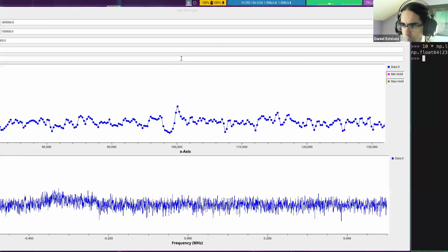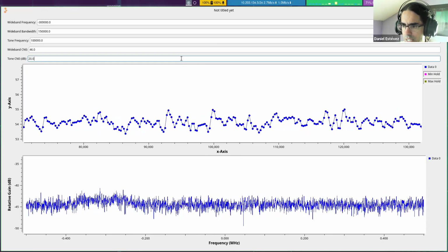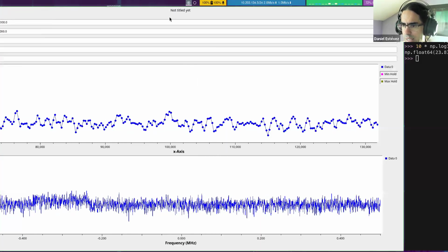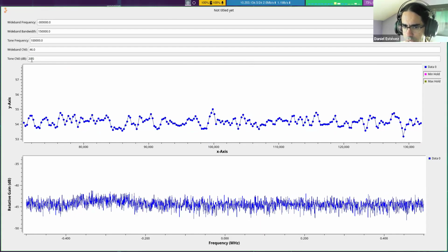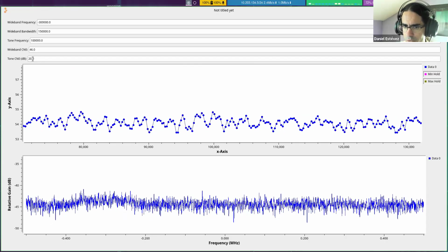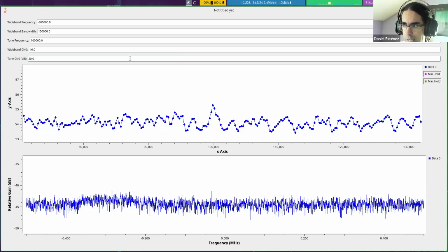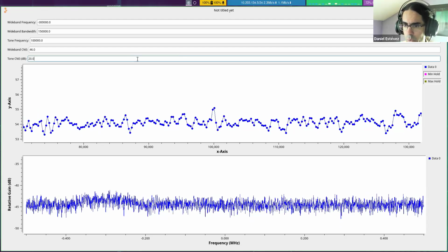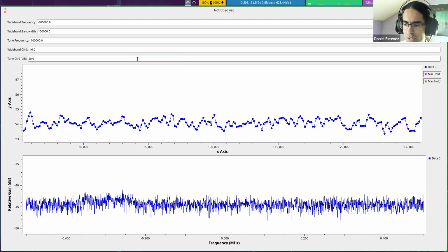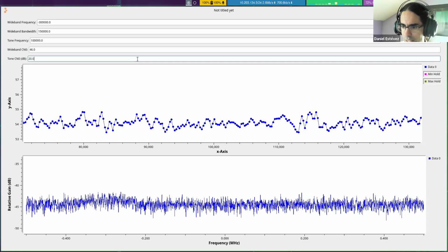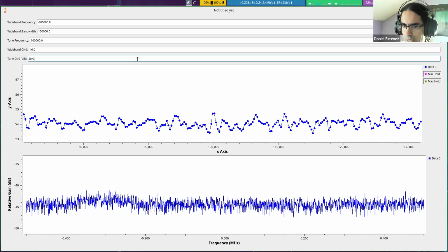I could do an example of changing the FFT size to, I don't know, 8 times larger or something like that, and then showing that we can actually detect a signal of 20 dBs because the bins have become narrower. In the interest of time, I will not do the example. You can do it yourselves later. It's very easy. Just change the FFT size and play with it, see what happens.